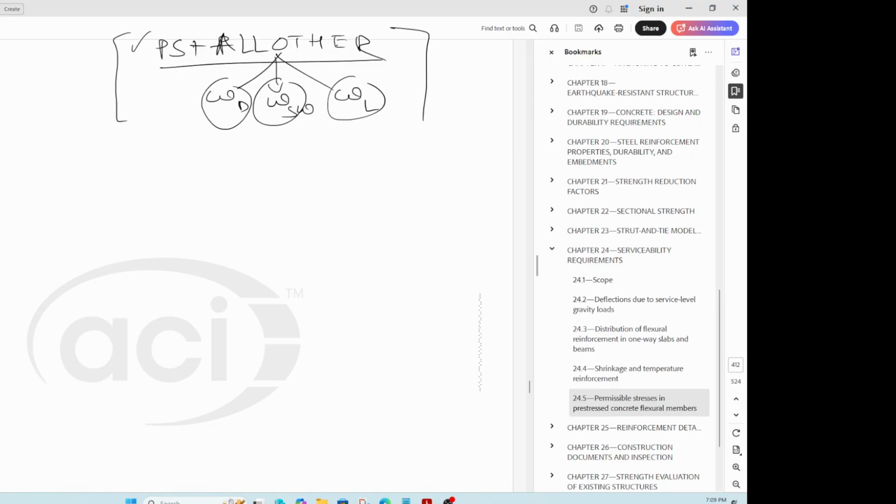So that means your beam is ready. You did the pre-stress cutting, so there is compression there, and you installed a deck slab already on it, so that is causing WD, the superimposed dead load. The beam is already concrete and it has self weight, that is causing self weight. Plus you are allowing a vehicle to pass. Let's say you have opened the bridge for traffic, right? So now you have a live load component as well.